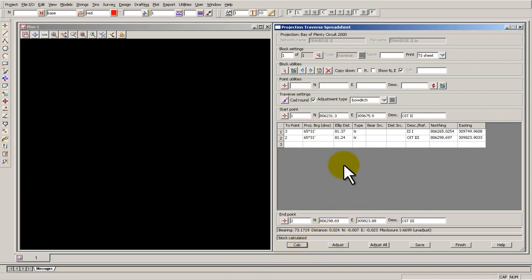6531, 81.37, and 6531, 81.24, 806.298.69, 309.823.88, and I'll just check these again, 309.675.9, and 806.231.3. So that's everything, seems to be in order. Just save, and that's an 0102 close, 1 in 6,000. That's pretty good considering what's happening there.